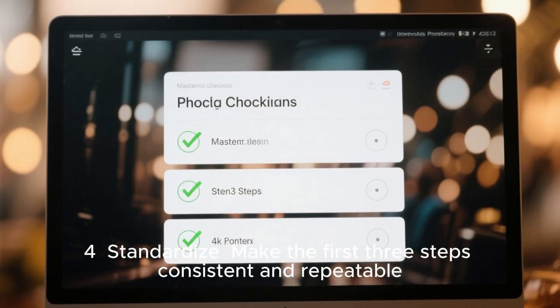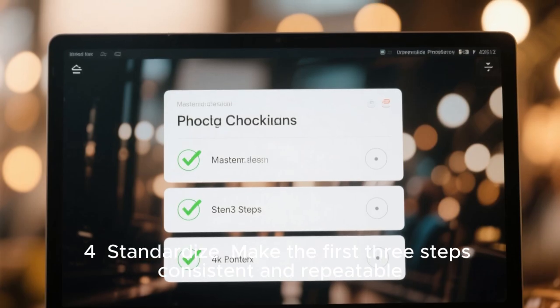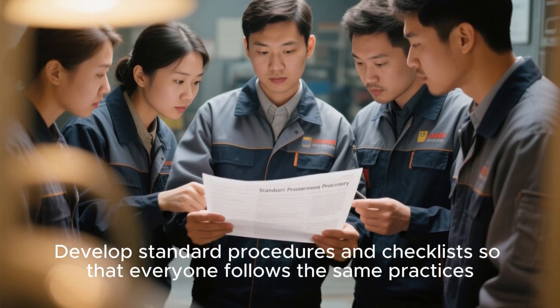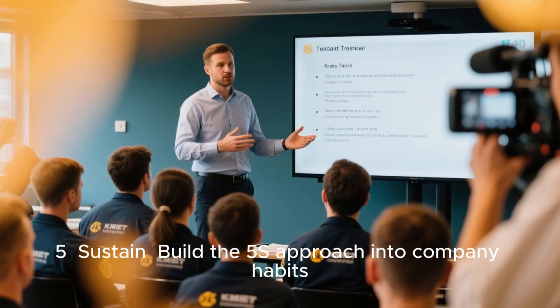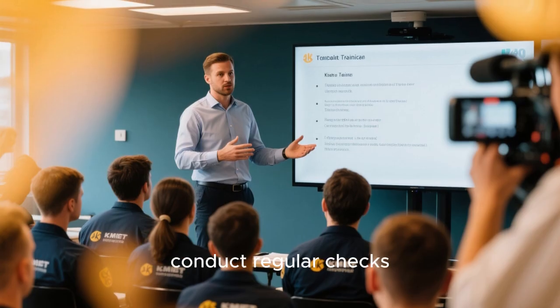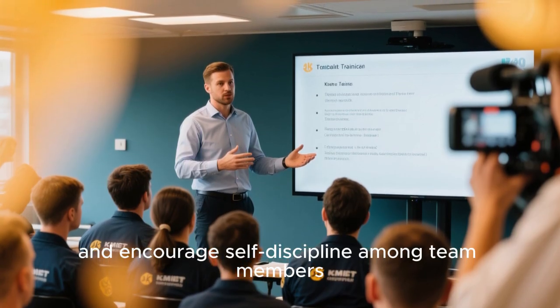4. Standardize. Make the first 3 steps consistent and repeatable. Develop standard procedures and checklists so that everyone follows the same practices. 5. Sustain. Build the 5S approach into company habits. Provide training, conduct regular checks, and encourage self-discipline among team members.